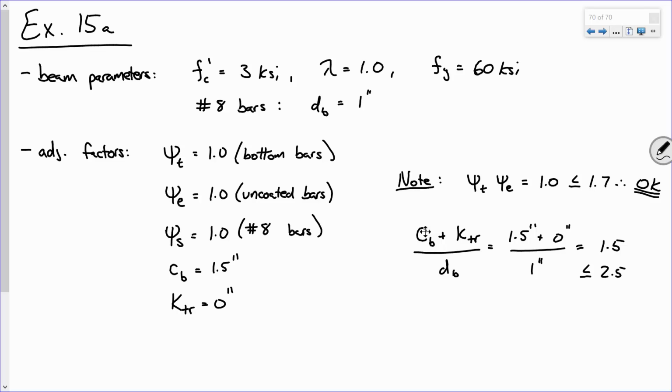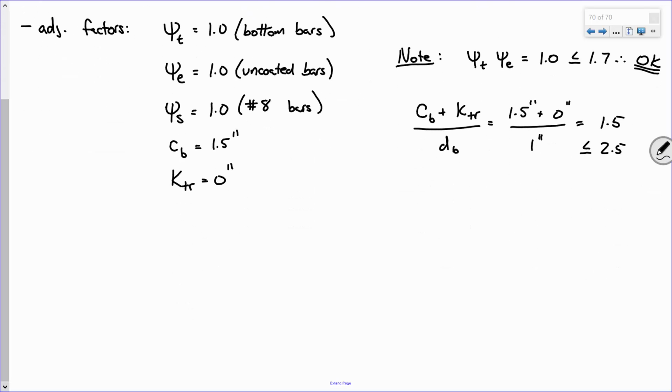It depends on how much of a benefit you're trying to account for in your shear stirrups. Like if you've got, let's say, a really heavily shear reinforced beam, that is possible. And basically what they're saying is, sorry, that can't happen. So it's possible. It is. Like our next example, we don't hit it, but we get like 2.3. We get close. Sound good? All right. So we're actually ready right now to go ahead and compute our development length.